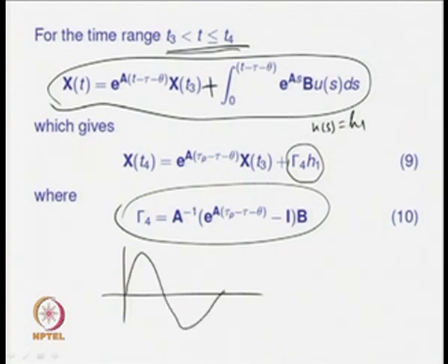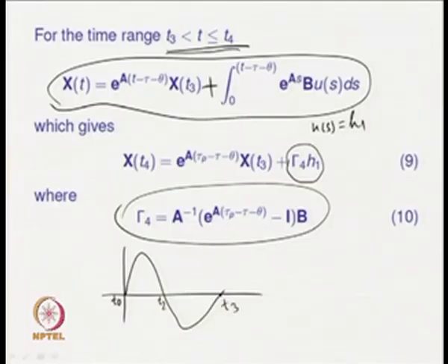So, for the 4 parts of one complete cycle, which is coming from t0 to t2 to t4, for different piecewise constant inputs, we have found analytical expressions. So, using this set of analytical expressions, it is possible to obtain the exact sustained oscillatory output we get from the relay test. Now, using those analytical expressions, we can find the unknowns associated with the same second order plus dead time transfer function model. Now, that effort will be made.